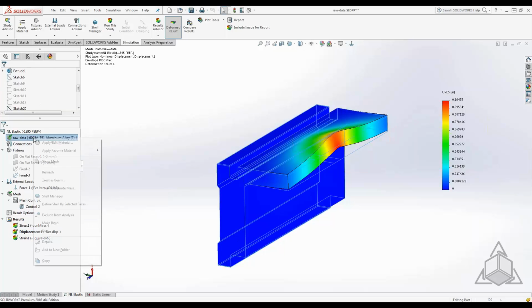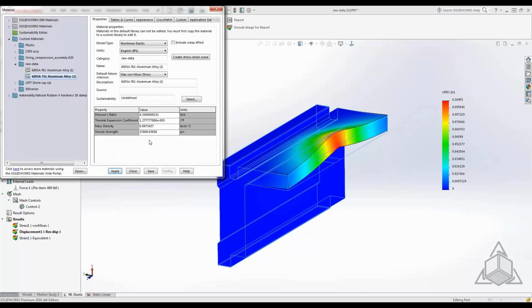So essentially, what the question was referring to is, what model type would you pick? Under plasticity, there are 3 types of plasticity: von Mises, Tresca, and Drucker-Prager. I do have more information on what is suitable for the type of plastic that you have.